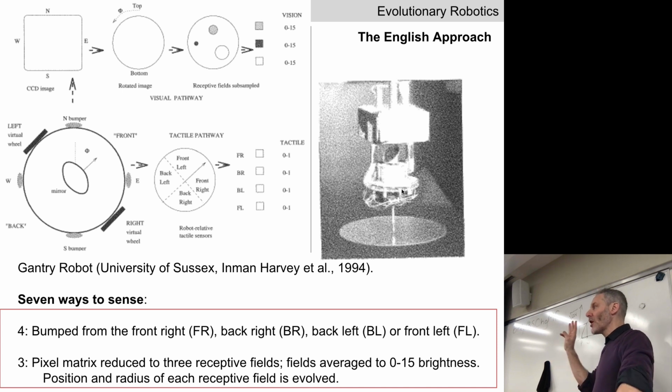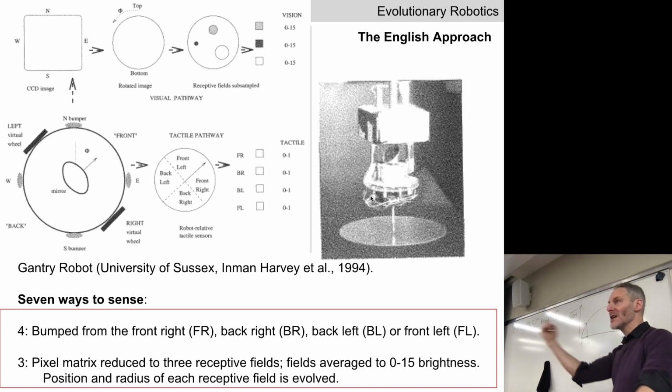I mentioned that there are 3 motors in the gantry robot. In the evolutionary process we're about to see, the neural network controller of the gantry robot only is able to control the first 2 motors. The neural network controller is only going to drive the 2 trolleys. They're going to set the 3rd motor to a constant angular velocity.